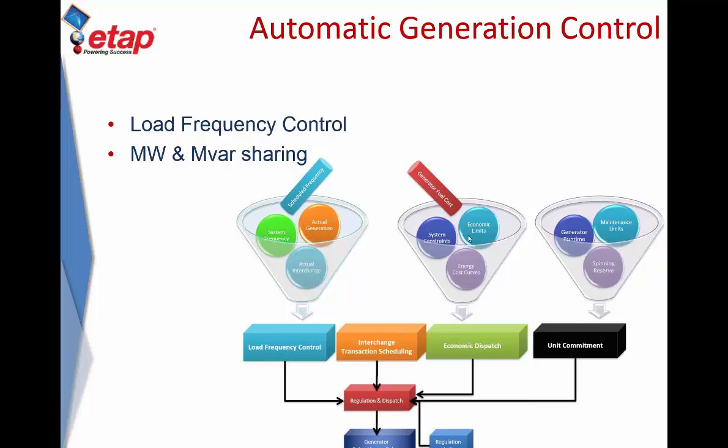isolated system. The economic dispatch essentially looks at the conventional generation fuel cost and economic constraints, and it looks at the energy cost curves from the power grid. Therefore, it's essentially looking at the tariff or the rate at which you're buying and selling power and the rate at which you're burning fuel to generate energy. And then it essentially decides which is the most optimal generation source and which source is closest to the load such that the losses are also minimized. So again, it's a multi-objective